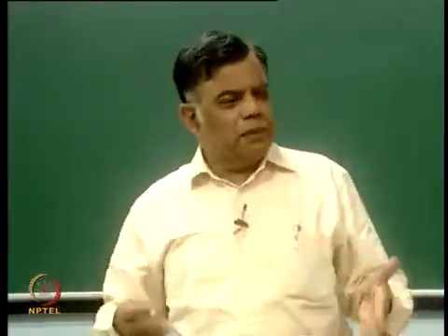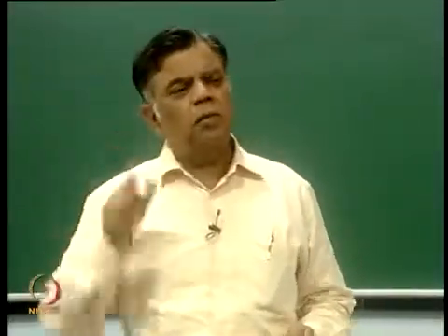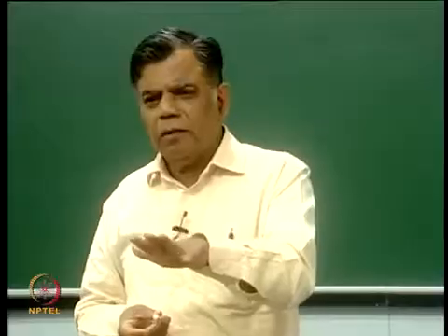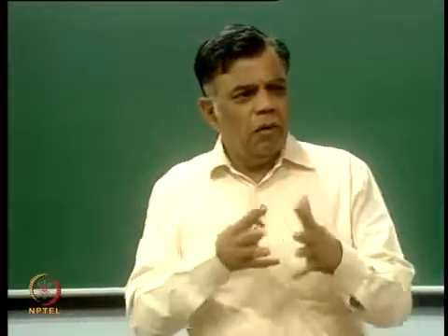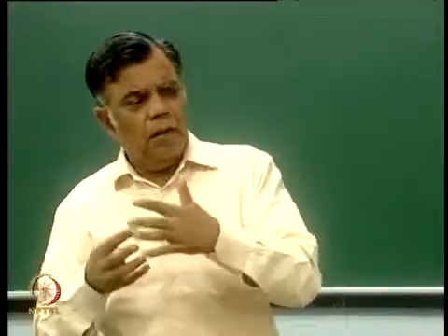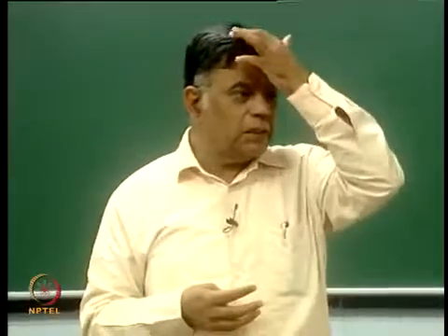Prandtl did another thing. I mean, he did not do it per se, but when he non-dimensionalized, when he made a scale analysis, he got this term μ/α, actually μCp/k. That is called the Prandtl number today. Now you see, over a period of time, from the fluid mechanics point of view, in 1883 Reynolds, laminar-turbulent transition came into the picture, and a number, the Reynolds number, came into existence.